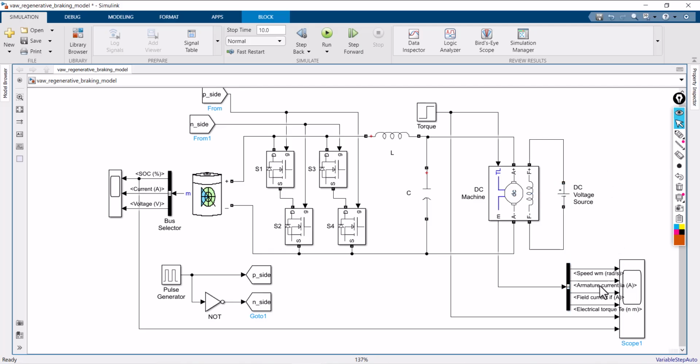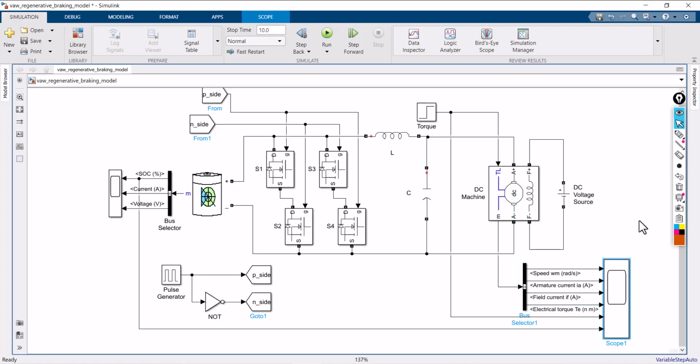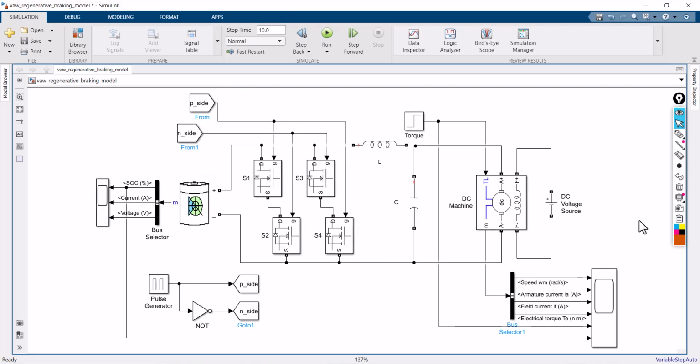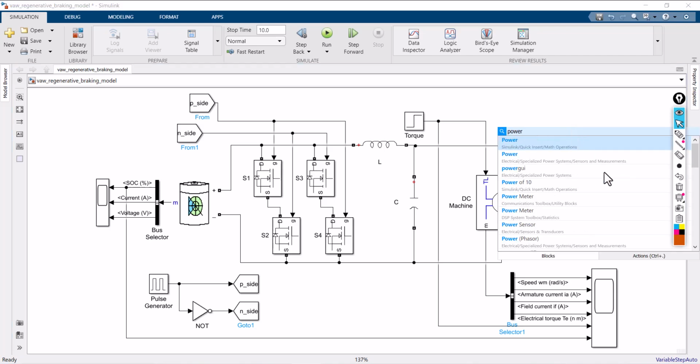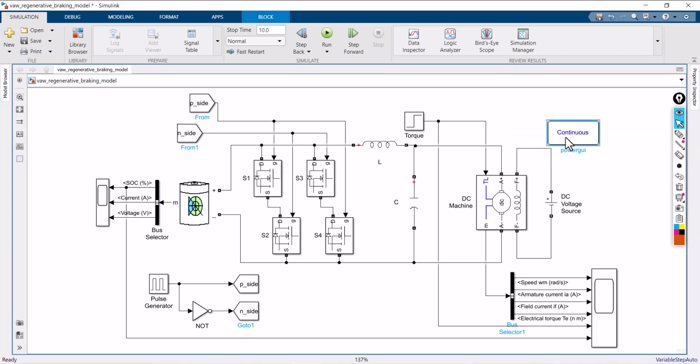Just organizing, just a minute. To run this block, you need a powergui. Powergui is mandatory. Just need to place it somewhere. So now I'm going to feed the inputs. We already declared what the machine actually is.